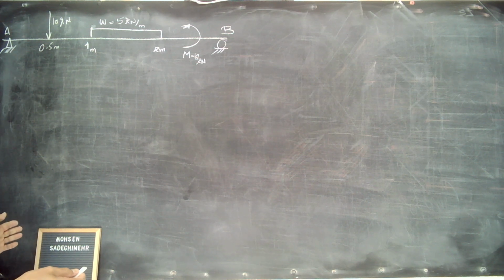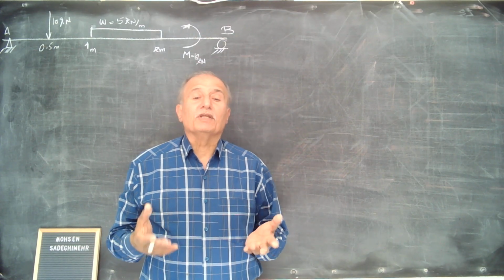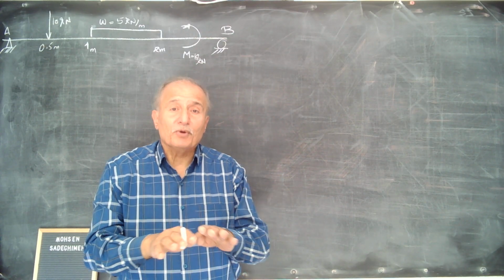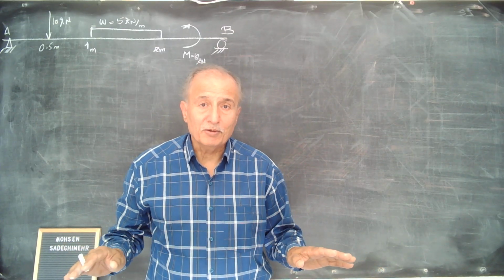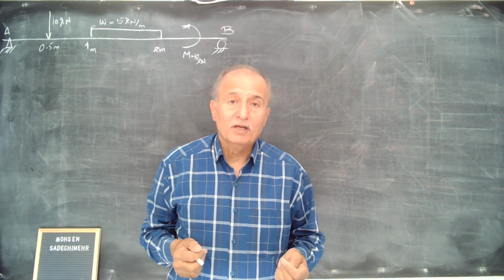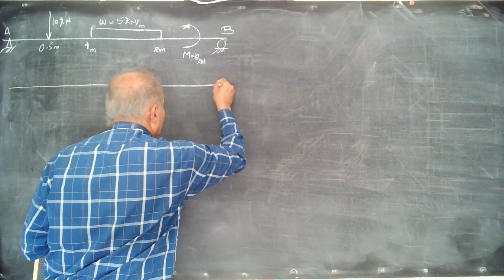Shear force diagram first. Before doing anything, you must draw the free body diagram. Free body diagram means separate all surroundings and supports from the beam and put the effect of them on the beam. Okay, let's draw the beam again.